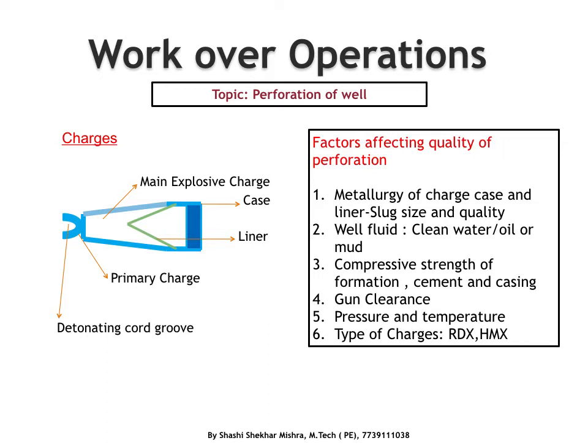Then comes the fluid under which the perforation is being done. If we perforate with clean water or oil, then it has a better flow index after the perforation than with mud. Mud based perforation causes plugging of the perforations, and they need to be cleaned out later to make them flow.